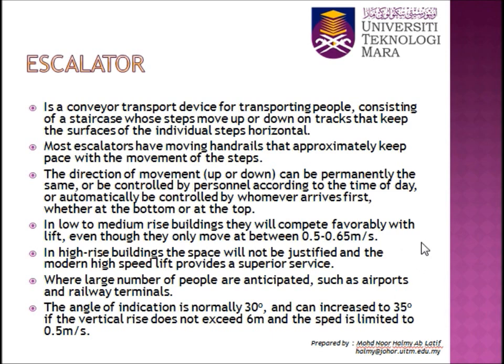Where large number of people are anticipated, such as airports and railway terminals. The angle of inclination is normally 30 degree and can increase to 35 degree if the vertical rise does not exceed 6 meter and the speed is limited to 0.5 meter per second.